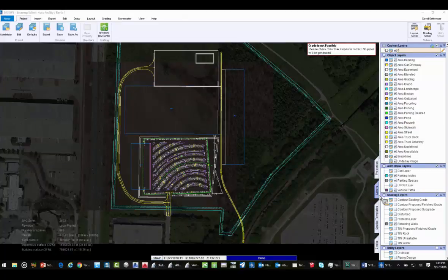So what I'm really getting around to is how the data is cleaned up before you bring it into SITEOPS. SITEOPS is not necessarily the place where you want to clean data. You want to use the tools. If I'm getting topography from a surveyor, they have all the tools and they should be able to clean it up really quick for you. Same as if I'm getting ContextCapture. Whoever's doing that work has the ability to quickly clean it up and make sure that the trees maybe are visible in the aerial, but they're not part of the surface model. So again, just make sure you clean the data up before you get in there.